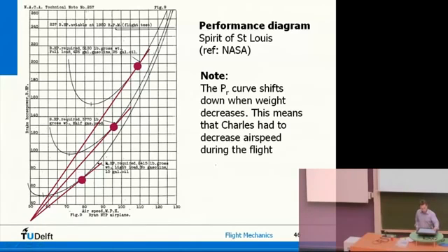So this is one of these power curves, and the point, if you draw a line from the origin over there, that's the minimum drag condition. So this guy, he couldn't look outside, so all he was doing was calculations on board to figure out how fast you actually have to fly to be in the minimum drag condition. So he was constantly doing these calculations. The flight took in the order of 30 hours, I think.